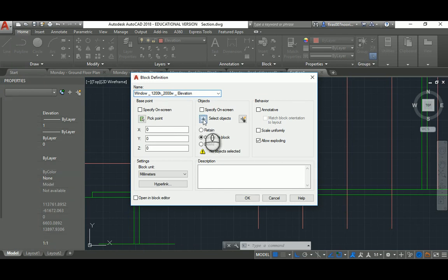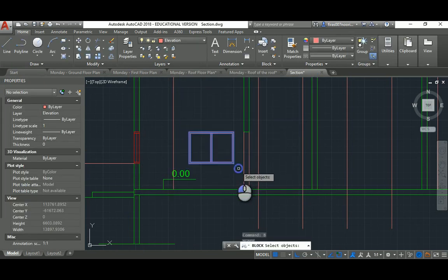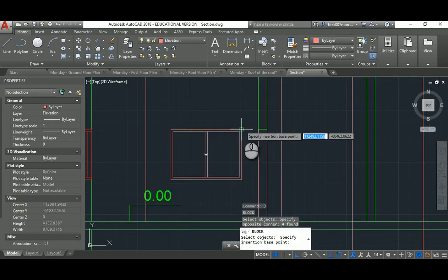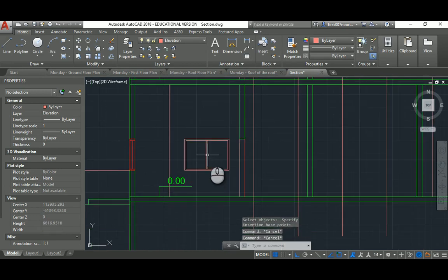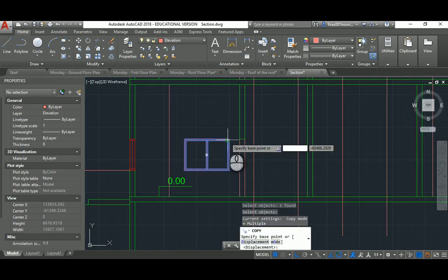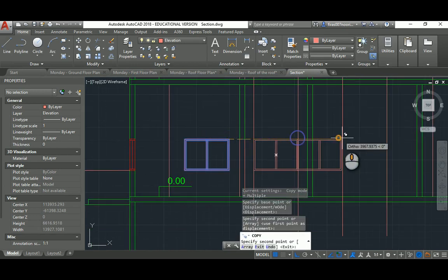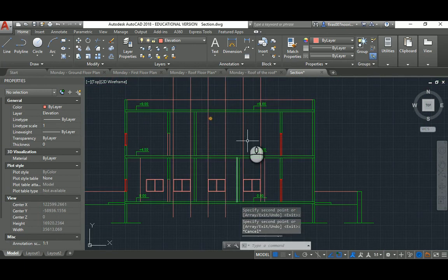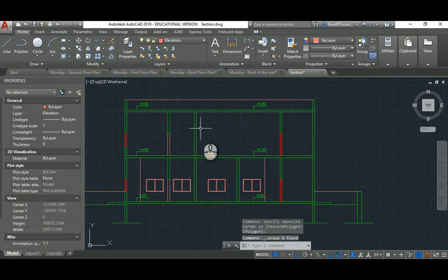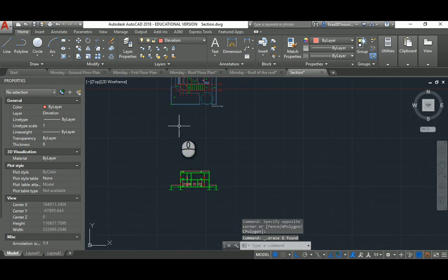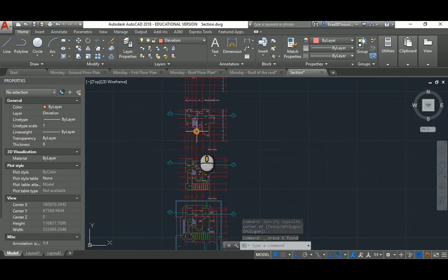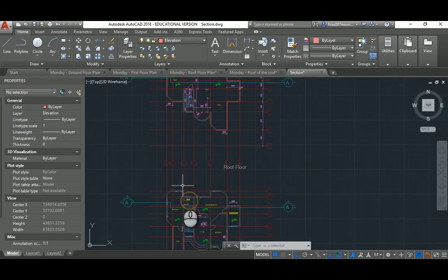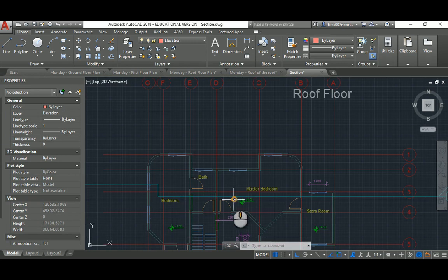You should place it in layer 0. I'm too lazy to do that, and that's the base point. Now you take that from the base and use F8, of course, don't forget, to distribute it to the entire plan, then get rid of the constructional lines that you drew, and then double check that you have the same opening, which is almost correct.